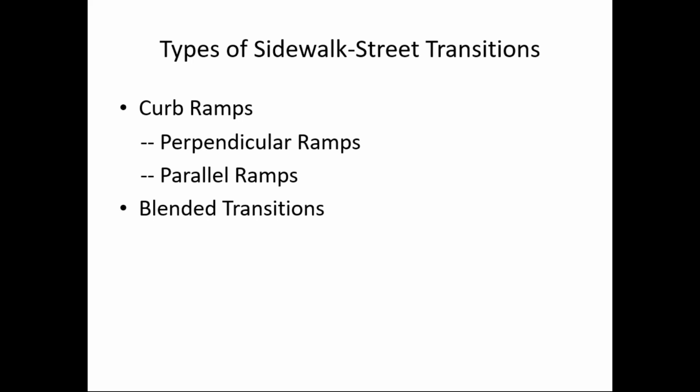There you have to be careful. But an entity could use ADAG for its public right-of-way. An entity could choose to do that. But if they choose to do that, they have to use ADAG in its entirety. So for example, in ADAG, the design user is someone in a wheelchair, so the minimum width of an access route in ADAG is 3 feet.